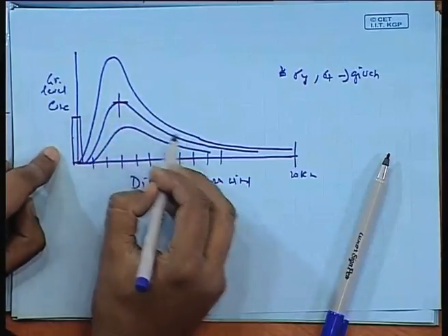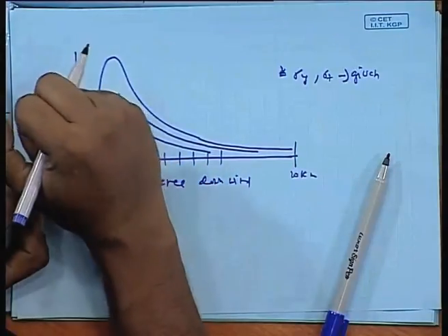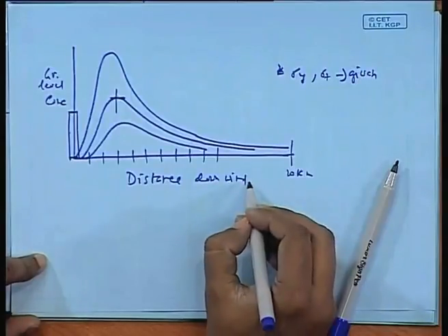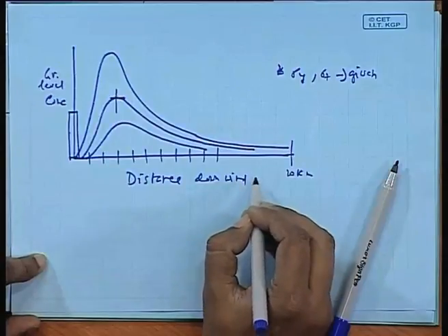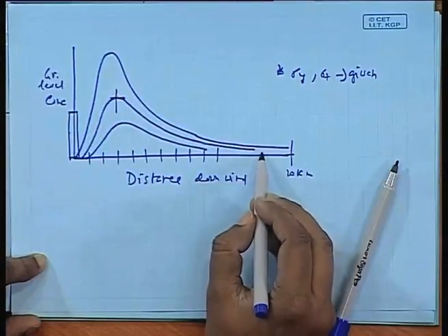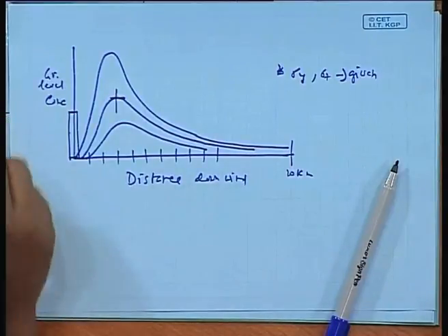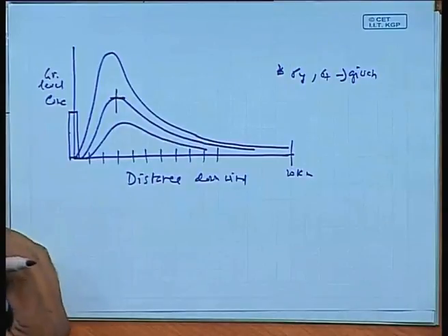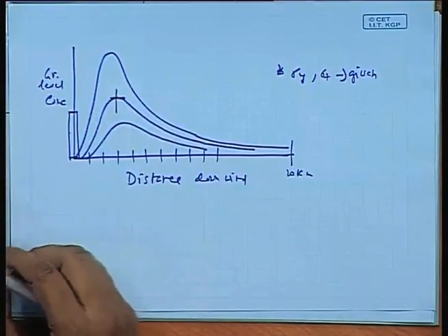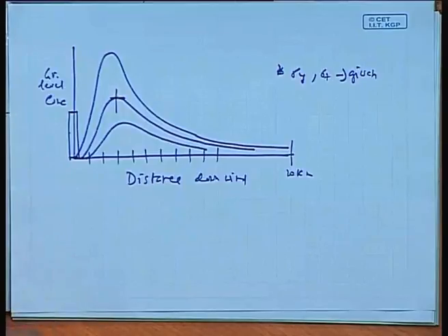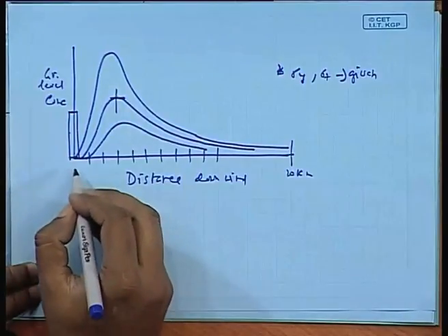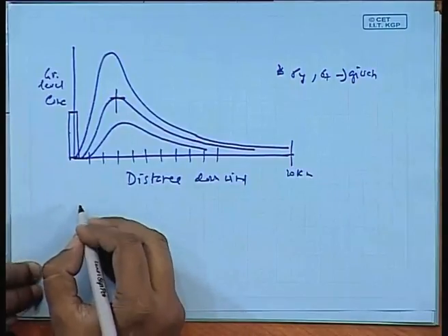And then it continuously goes down, which is expected, because the larger the distance, the more the concentration is reduced. So this is the typical characteristic that we can observe using this Gaussian plume distribution model. This model suits most atmospheric concentration calculations, and another important thing is that for point sources, the Gaussian plume distribution is applicable.